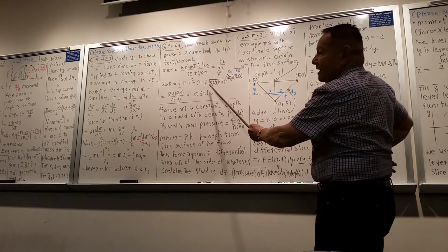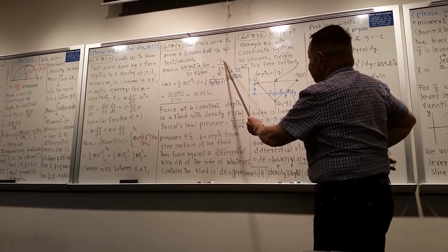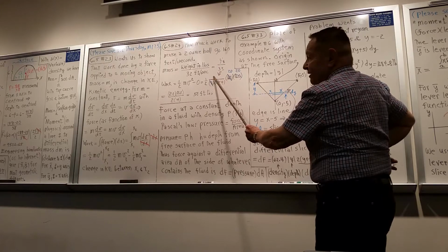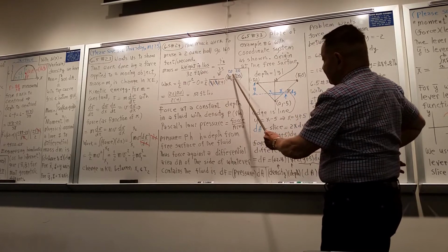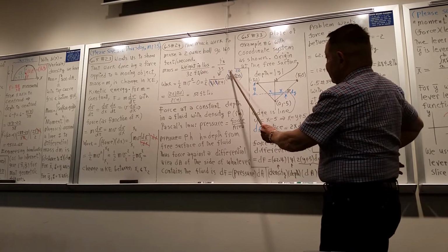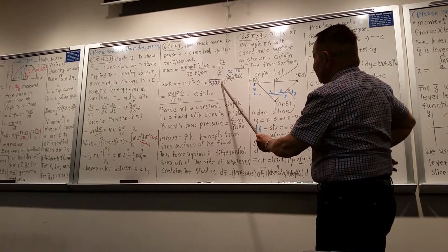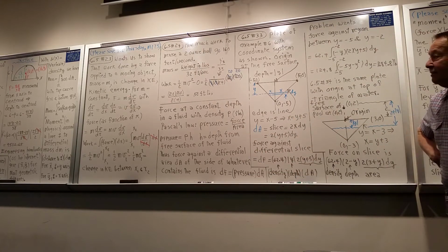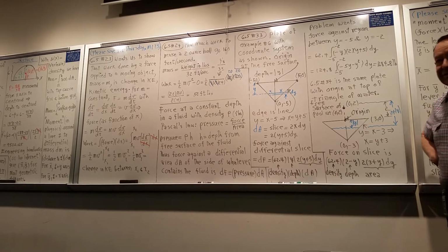Then you can do some canceling: you have 1/8 times 32, and I wrote the 32 as 8 times 4, and I can cancel each 8 into each 160. So I have 20 times 20, and I have 2 times 4, and so I get 50 foot-pounds. So with the formula, these are not that hard to do. Problem 25 is similar to this.